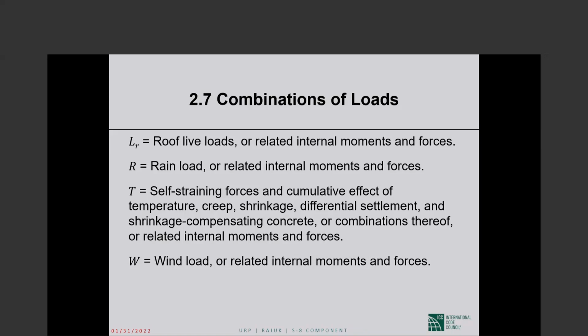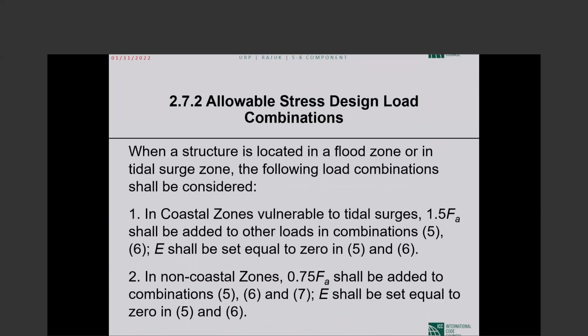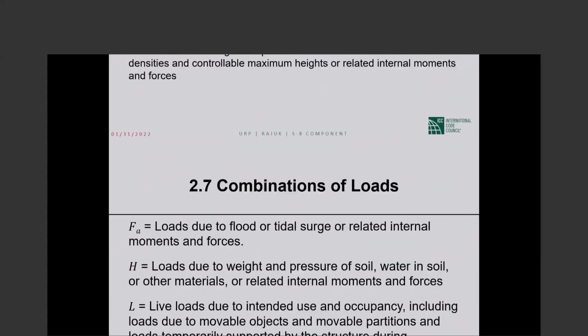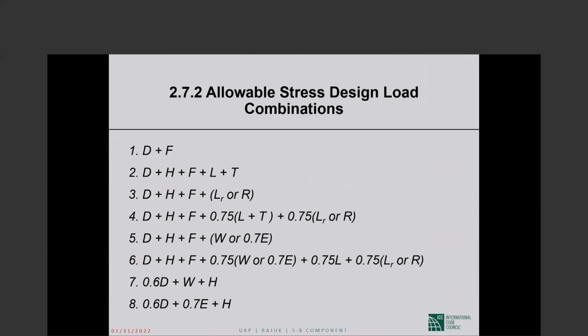Concrete is weak in tension. So you are now looking at cracking. And unless you have provided adequate reinforcement, the cracking may cause very serious problems, including failure. Okay, so T, the effects of restrained shrinkage, restrained volume changes, has to be taken seriously. W is the effects of wind loads. Those are all the terms that there are in this equation.